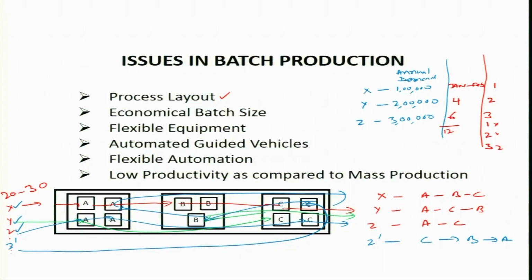So, if I say this is my option A, this is my option B, the question arises which one I should prefer. In option A, you will find the changeovers are very few, only 3 changeovers in a year, but the cost of carrying inventory is very high. Something you are producing in January and consuming till December. So, the cost of inventory is very high, whereas the changeover cost is very low. Whereas, in case of B, you will find the cost of carrying inventory is very low, because you are producing in very small quantities, but you are doing almost 3 lakh changeovers in a year.